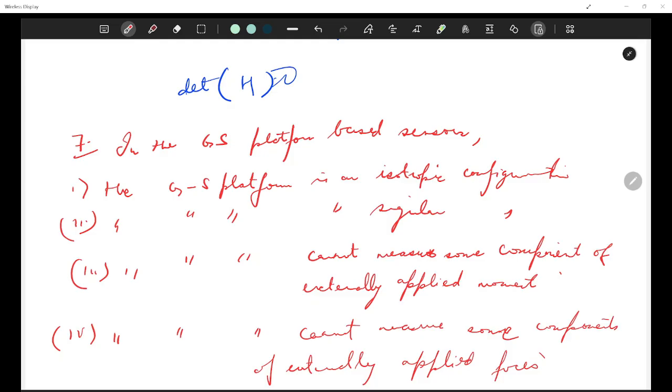Let's start. First, what was special about the sensor design? In motion platforms, when we want motion, we usually say we have achieved singularity and that is a problem. Singularity is bad. It causes loss of stiffness. The platform becomes uncontrollable. But in the sensor application, something different was done, right? The platform was placed in a near singular configuration intentionally. Why?